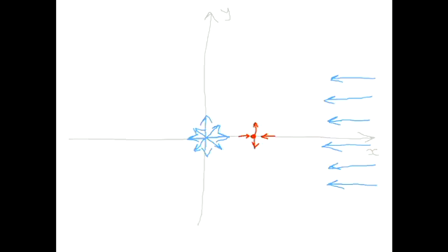So we worked out where that stagnation point is, and I'm telling you that stagnation points are always saddle nodes, okay? So there's always two streamlines coming in and two streamlines coming out. And I don't know which way round that is. There could be two coming out this way and two coming in this way. But it's always going to be a saddle node topology, which is going to help us sketch this flow.